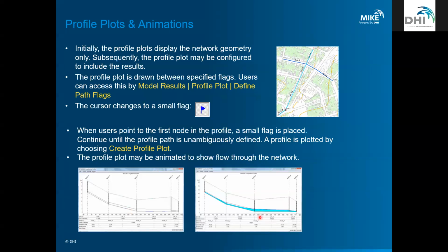the network is operating. You can see, if you have flooded manholes, you'll see the water level can get up to here. And you'll notice that maybe you need to put a siphon in the network or some other option to prevent the flooding there or change the manhole type. So this is a really useful tool, and you can step through quickly as a full animation, more like a movie, or you can do a step-by-step step through, and so you can find the specific point where the network is flooding or there's no flow through the system. It's really good for analysis and troubleshooting in problematic parts of the network to physically see it.